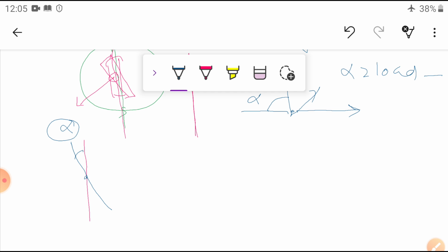So what is the purpose of alpha? Under no load condition also alpha is present, to meet the stationary losses, that is, the iron losses and the windage and friction losses. This is known as the coupling angle, synchronizing angle, power angle, or load angle.